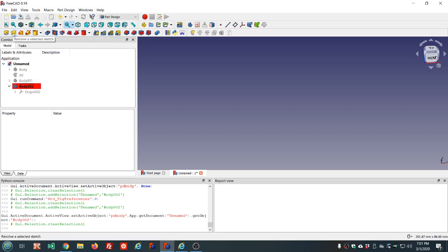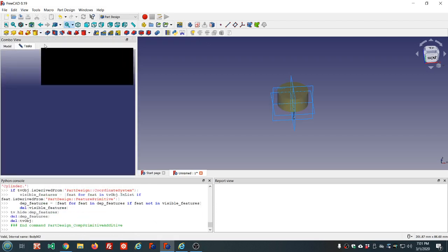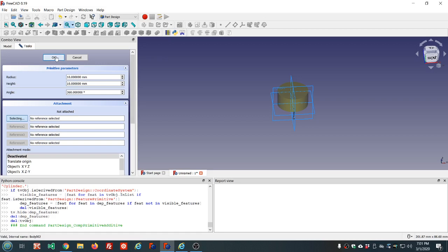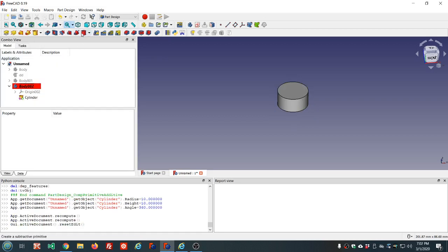And this is the revolve that we used a moment ago. Groove is the same thing as revolve, except it's like a subtractive revolve. So it does a revolve and then cuts it away from what you had before. Then you have the loft and sweep, additive and subtractive versions of each of those two. So we're going to make an additive cylinder of the outside part, the outside cylinder, and a subtractive cylinder of the inside part.